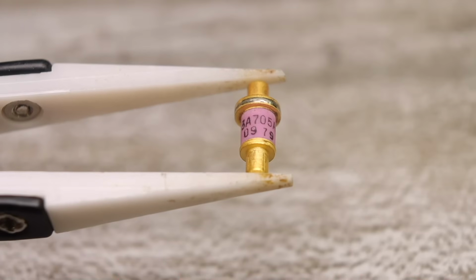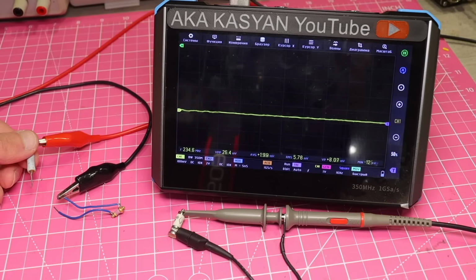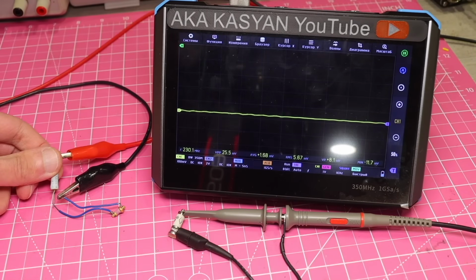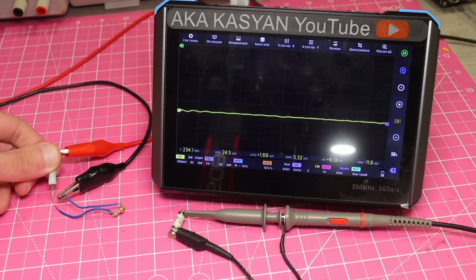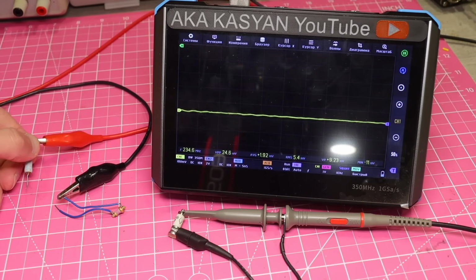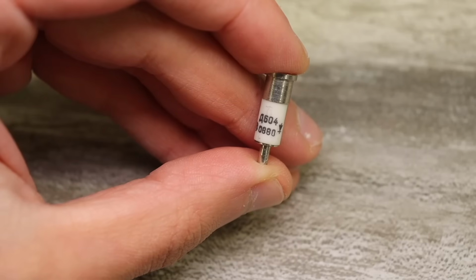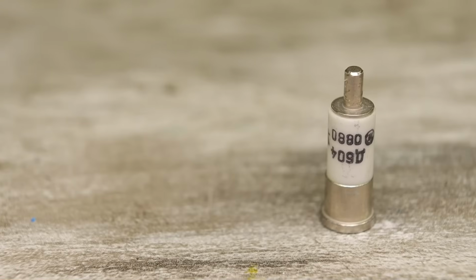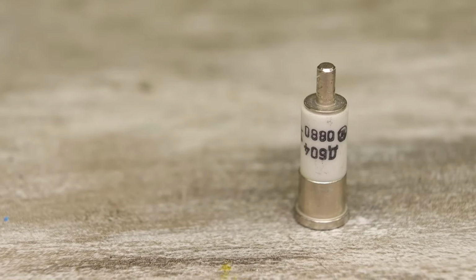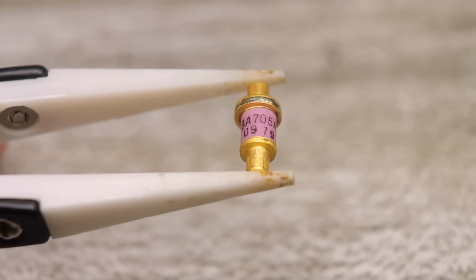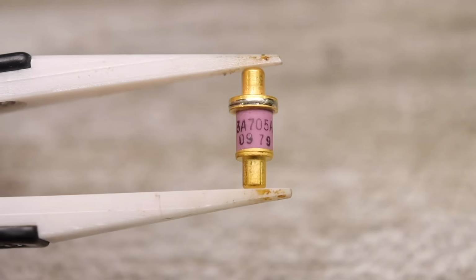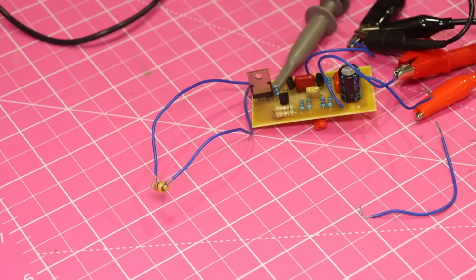Actually, to check if it works, it's enough to apply a certain voltage to it with current limiting. The wires and connections create parasitic inductance, and you will get at least some radiation, and you can detect this radiation using a detector diode that can operate at such frequencies. But if you want it to work properly and efficiently, and to be able to adjust the frequency, you'll need to build a power supply circuit and make an antenna.